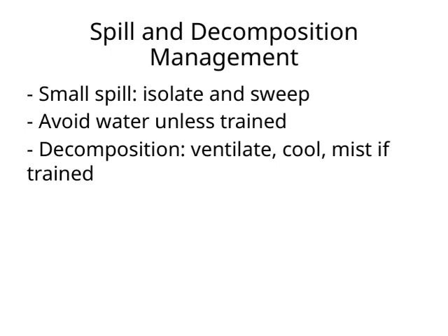When it comes to small spills, the first step is to isolate the area to prevent the spread of any hazardous material. Once isolated, carefully sweep up the spill, making sure to avoid creating dust or aerosols that could be inhaled. It's important to remember that we should avoid using water unless you are specifically trained in its safe application, as water can sometimes react with certain substances and make the situation worse.